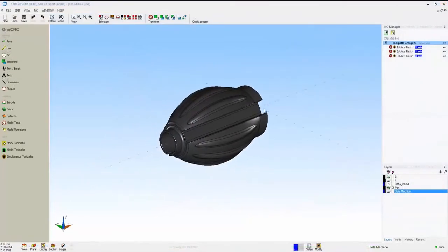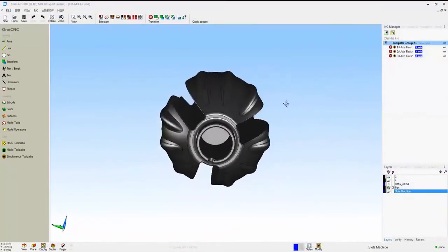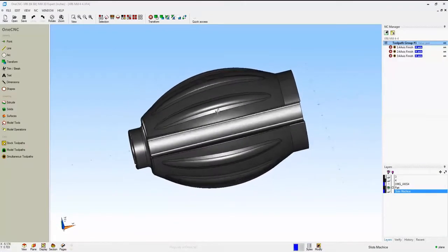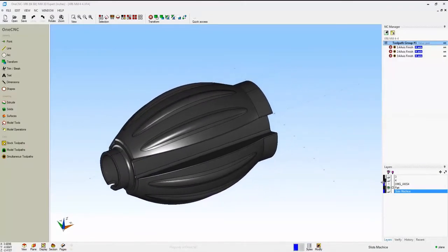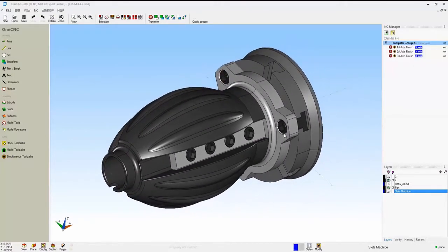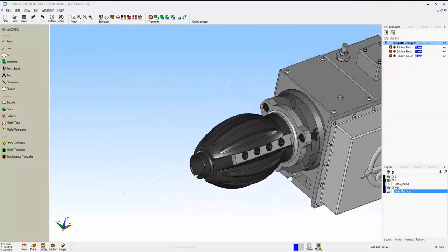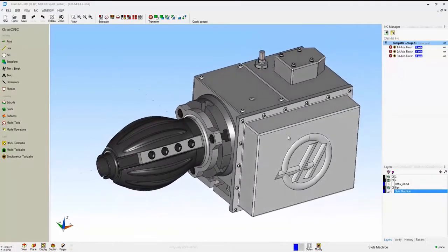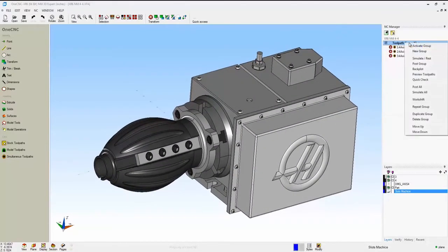This is a little bit different. Let's take a look at this part. This is where you're performing surface machining and your A-axis moves at the same time. So what we're going to do is apply toolpath that's going to be collinear with the center of index. All the tooling setup's exactly the same that we looked at before.